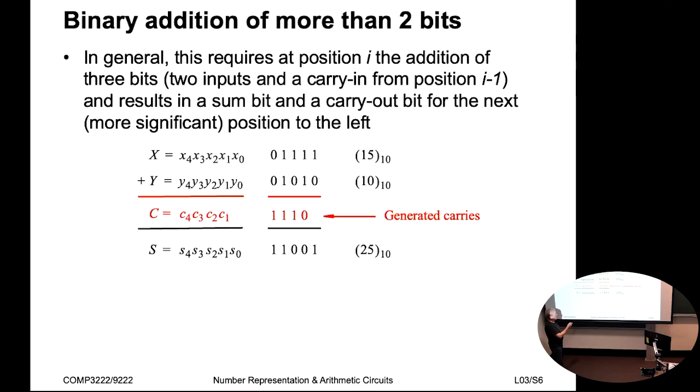So in this particular case, when we add 1 and 0 together, we get a 1. And in the next bit position, when we add 1 and 1 together, that's of course a sum of 0 and a carry of 1. The result's 2, so it has to be binary 1, 0 as the result. So the carry that we get in this case is a carry of 1, and the sum bit is 0 down here.